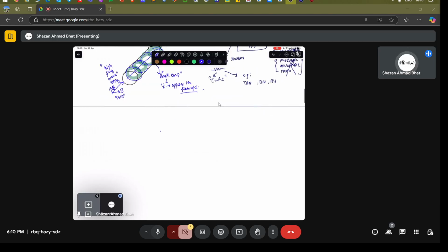That means if you have, let's say, a metallic bar of certain thickness, and you feed it with an electromagnetic wave, we're talking about microwaves here, okay, then the current is going to flow over the surface and it's going to penetrate into the bulk, into the depth, very minutely, depending upon the frequency and the resistivity of this metal. The depth is called the skin depth. Okay, up to which it penetrates into the wire deeper from the surface, from the periphery. That is called skin depth, or it may also be called penetration depth.